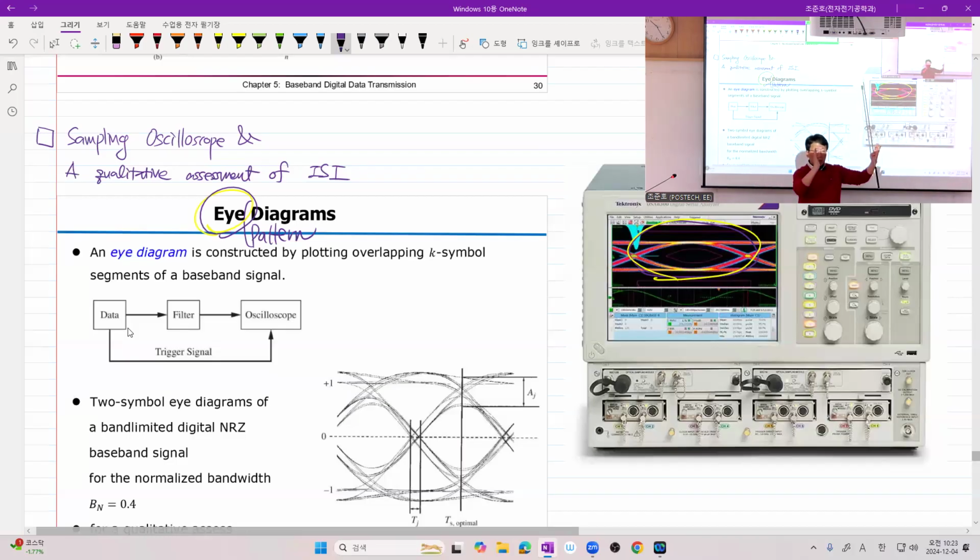And maybe it is not exactly aligned, but depending on your equipment and its options, if your signal is one of the optional signal inputs, then your oscilloscope automatically finds the timing and delays the signal so that you have a beautiful eye centered on your screen. Sometimes you use, for example, half of the symbol rate. Then you have one eye here and half of an eye here and half of an eye here, something like that. Got it? So it depends on the setting of your oscilloscope.